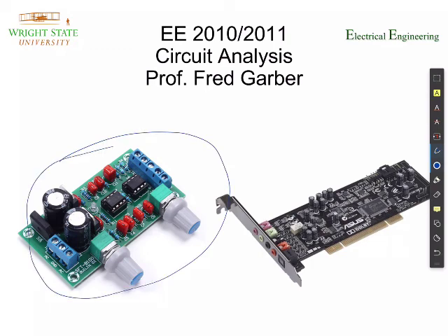So here is a bit of a standalone sound card, and we see some amplifiers and capacitors, those little orange things, and variable resistors, the things with knobs that are working with the amplifiers to adjust gain and maybe some tone, some frequency domain processing. And then resistors, those blue things all over the place with stripes on them. Oh, also these big can things are just larger capacitors, bigger cousins of the orange ones.